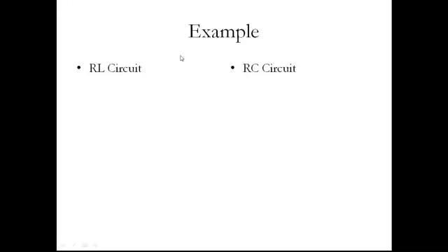First, let us understand the RL circuit and RC circuit with sources. We have a source called Vs, with R and L. I told you that when an RL circuit is given, you are interested in finding the current through the inductance, so you write only KVL, not KCL. Writing KVL: minus Vs plus IL times R plus L into dIL by dt equals 0. Organize this equation.